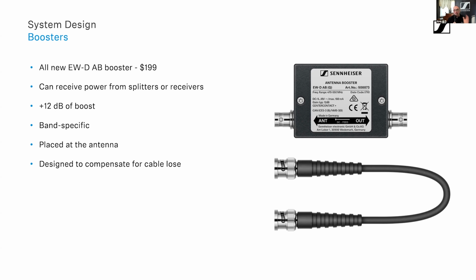Now, one thing we want to be very, very clear on about boosters is that boosters are designed for one thing and one thing only, and that is to compensate for a cable that has too much loss. When you use a booster, you are increasing not only your signal, but also the noise floor. So you only want to use a booster when you absolutely have to. It's always going to increase that noise level, and it's not really the best thing to do.